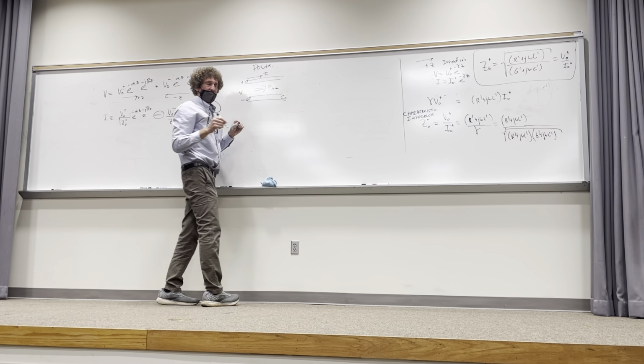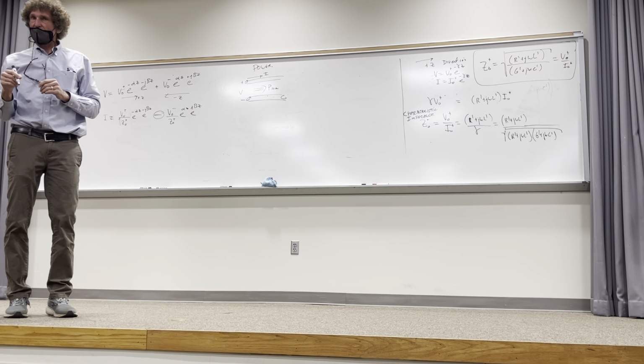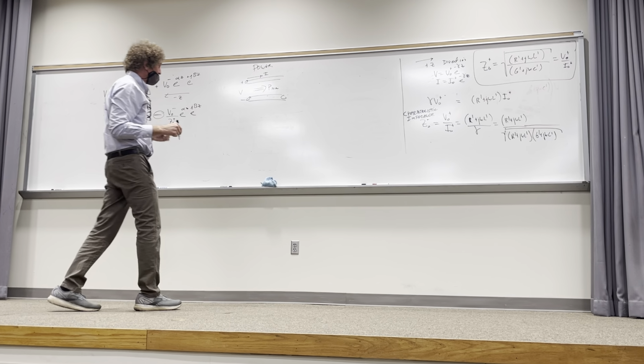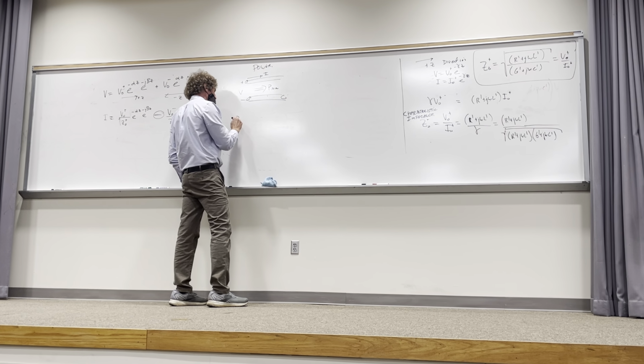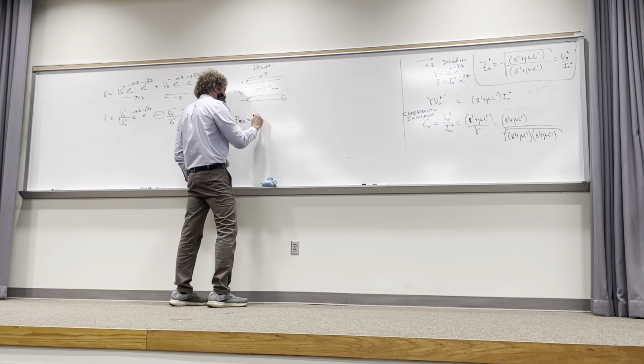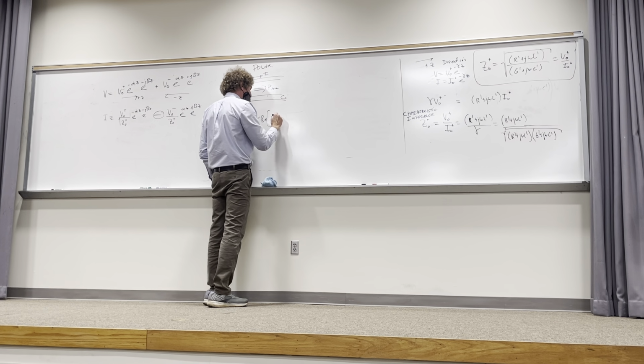We're always worried about average power flow. We don't care about peak, but we care about average if we have a sinusoidal variation of the excitation. So when we talk about average power, that's equal to 1/2 the real part of V times I conjugated.